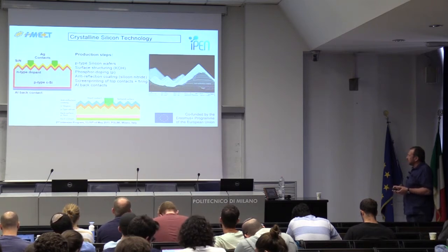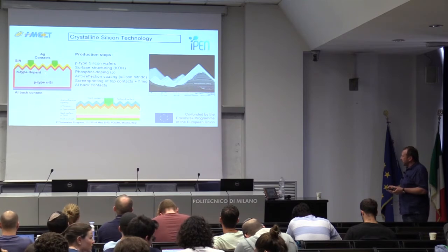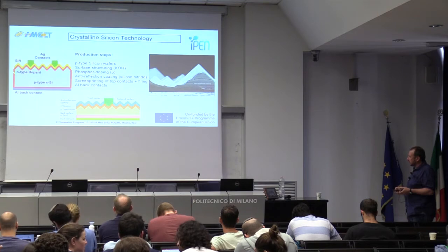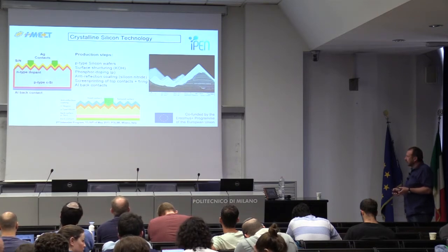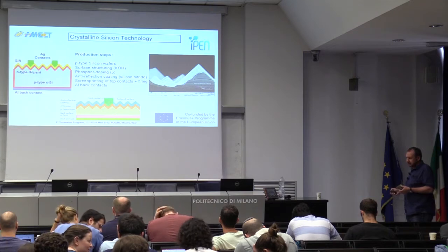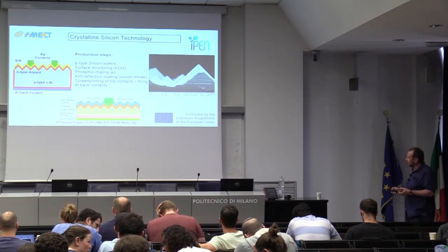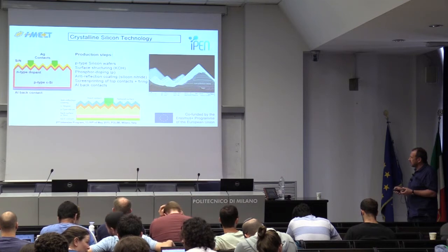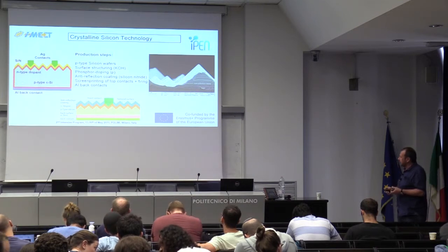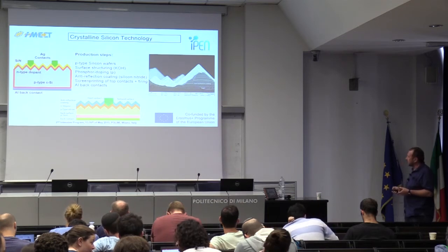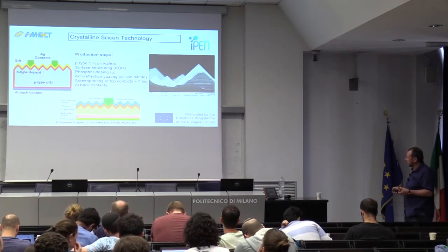Now, after that, there is a phosphor doping step with phosphor oxychloride, which covers the surface, and after heating up, phosphor is diffusing into the silicon wafer, shown here with this red line, and it obviously surrounds the whole silicon cell, top, bottom, and also sides. And these sides are a problem for the further production, because they have to be isolated. I will show it on the next.